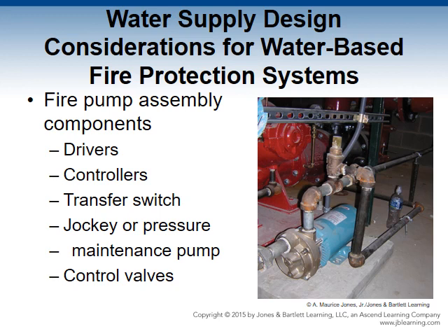Next, you have bypass. Provide a pipe path around the pump in case the pump fails to operate. Requires water control valves and check valves that prevent water from flowing back into the water supply systems. They should remain open and only be closed when the check valve requires maintenance or service.